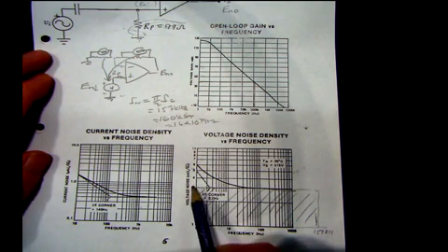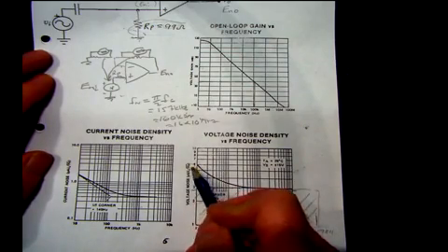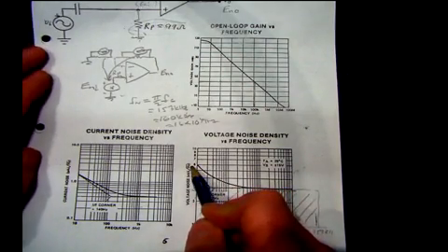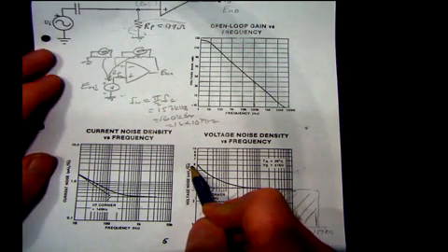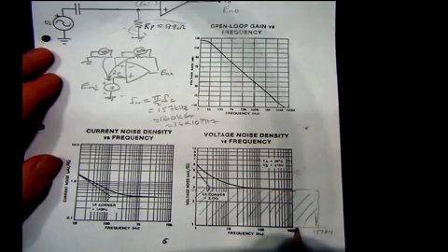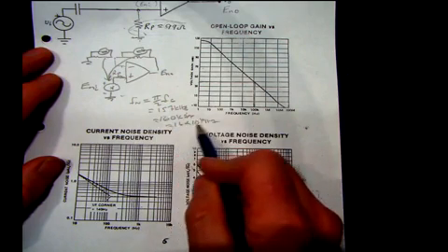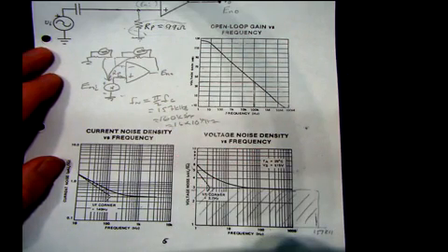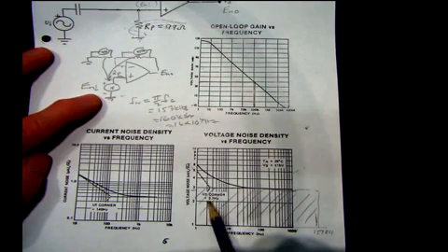With these crazy units of nanovolts per square root of hertz, all we need do is multiply by some square root of hertz, and then we would get the right sort of value. So if we multiply by the square root of 16 times 10 to the 4th, that's 400, then that would give us an idea of the voltage noise that we would see sitting at the input just due to EN.